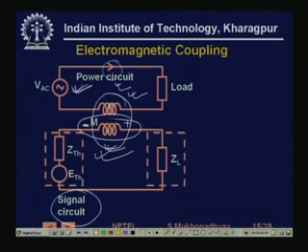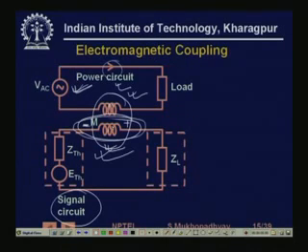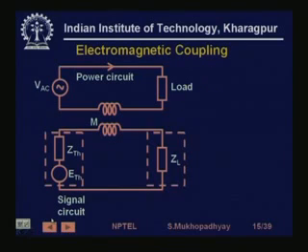So they can induce quite a lot of voltage into these coils. Now there are various options. For example, you can try to magnetically shield these circuits, but that may be quite expensive. So one of the ways is that whenever we transmit, if you transmit our signal in terms of current and not in terms of voltage, it becomes much more immune, right.